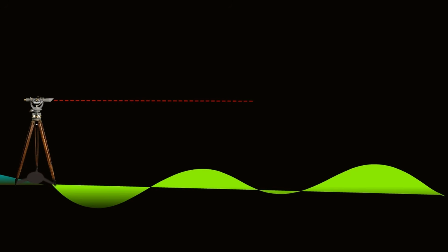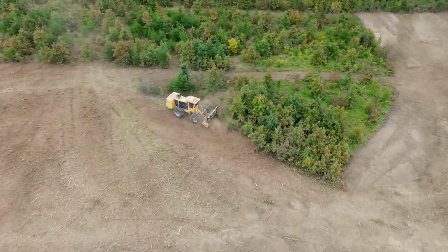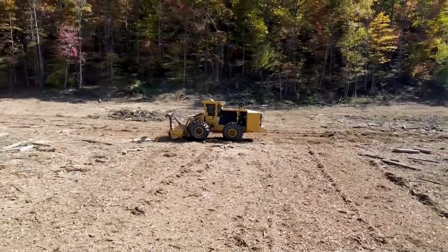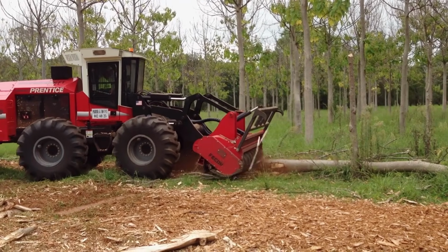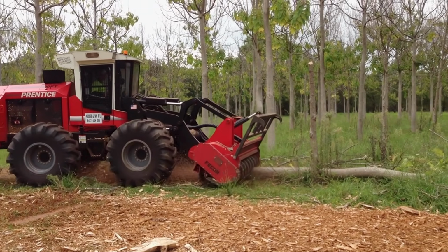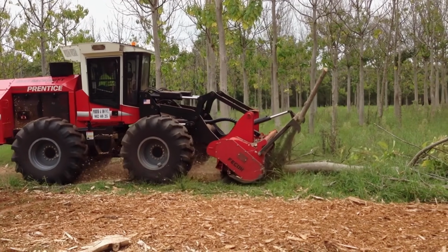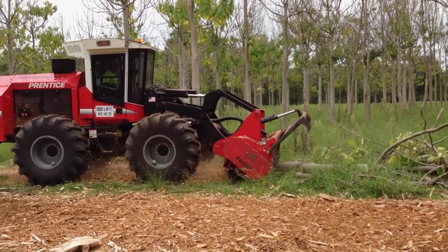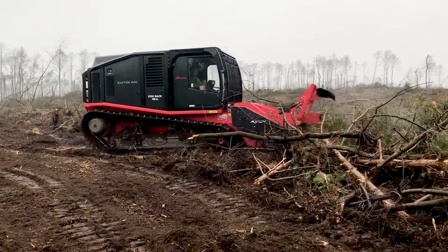These levels help in calculating the quantity of excavation carried out during the cleaning process. Usually, the subgrade requires basic preparation to make it suitable for construction. This process is known as subgrade formation or reducing to level. It is a bad practice to construct pavement over surface vegetation or topsoil, as it contains organic material. This material will decompose over time, which can lead to the formation of voids in the layers above, resulting in settlement of the pavement.